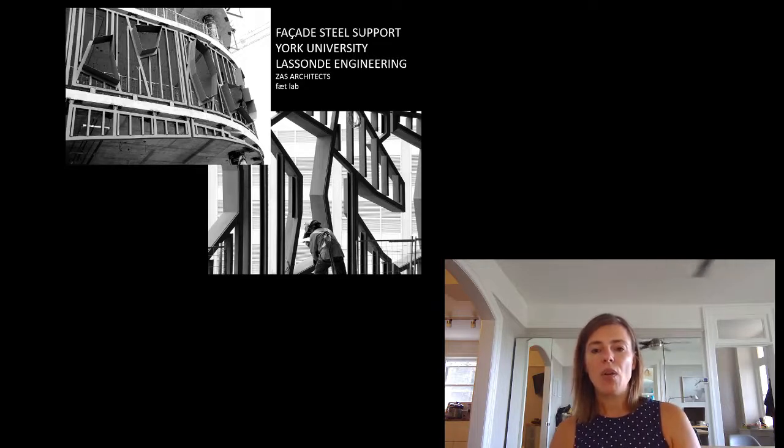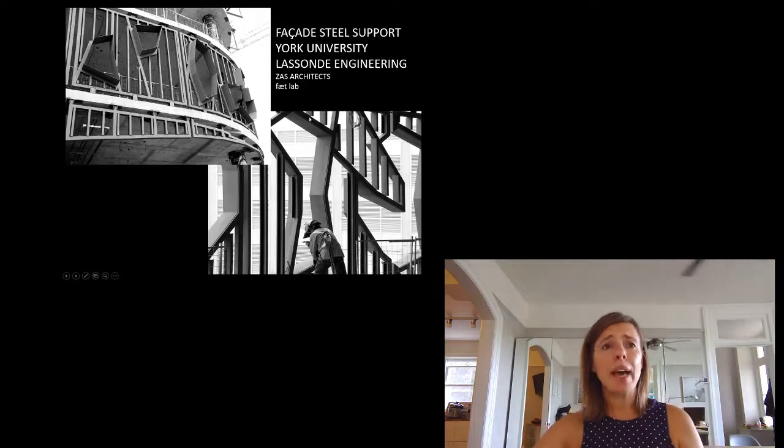I said, okay. So I stopped by the site, took a look at it, and saw the problem immediately. The problem was that this right here didn't matter. That was all going to be channeled out and covered by drywall, and was kind of irrelevant. The only thing that mattered, if you look at this picture, is what happens where the window plane is, so out along these edges. And you can see this particular one crossed two frames. The only thing that mattered, imagine if there was a break right here, is whether that point and that point were in line with each other. So we took out a ruler, held it out there, and could see that it was fine.